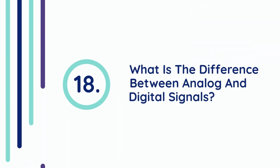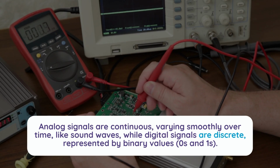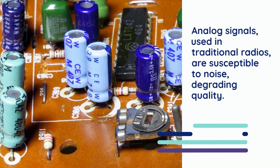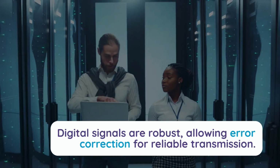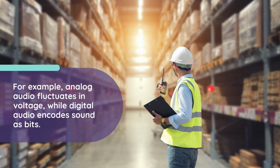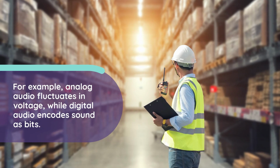18. What is the difference between analog and digital signals? Analog signals are continuous, varying smoothly over time, like sound waves, while digital signals are discrete, represented by binary values, zeros and ones. Analog signals, used in traditional radios, are susceptible to noise, degrading quality. Digital signals, used in computers, are robust, allowing error correction for reliable transmission. For example, analog audio fluctuates in voltage, while digital audio encodes sound as bits.